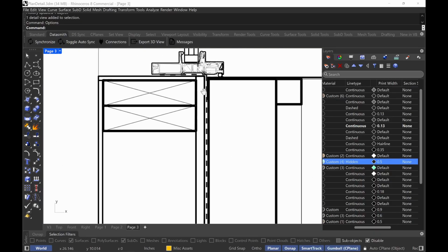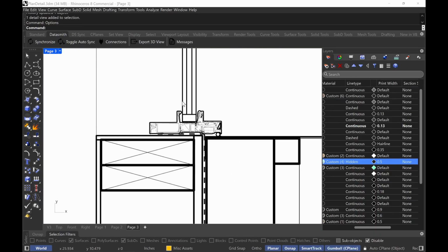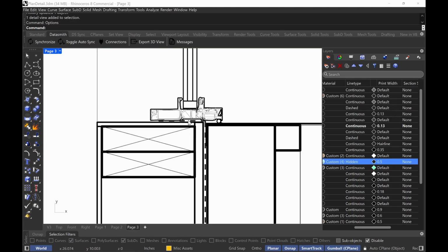If you notice here, for example, I have this nice thick outline around my window frame, right? And then if you see, I kind of exaggerate the gap of the actual window frame to the jamb. And in reality, I would probably add another nailing block underneath this. But some people will nail it directly onto there if they wanted to. But yeah, you would actually nail another nailing block on here.